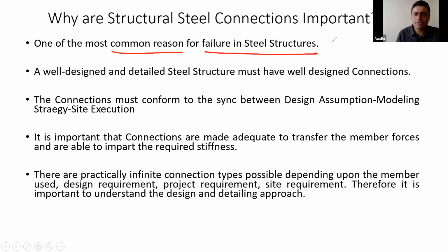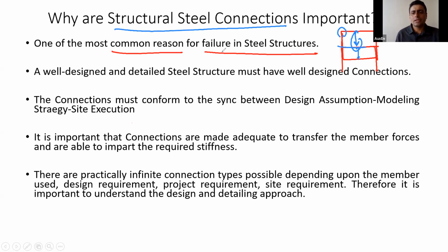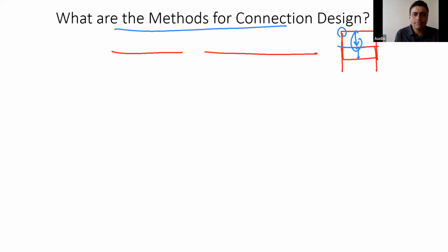Okay. So progressive collapse means that, let's say, if you have got a multi-story structure, and if this connection here fails, then this level falls, this level falls on this, then this level together falls on this, and so on. Progressive collapse. Okay, so moving ahead, these are some of the important reasons why structural steel connections need to be carefully studied and understood. So quickly moving ahead,